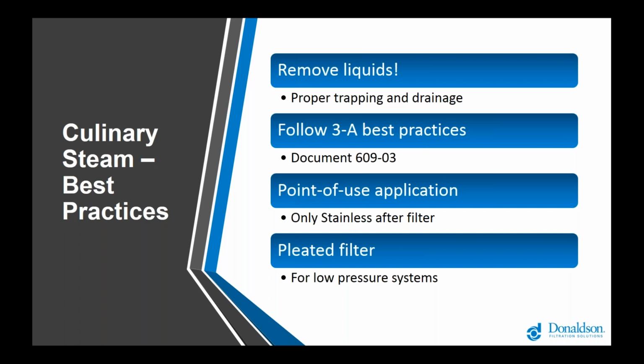And thirdly is use filters at points of use. So I've seen tons of systems where this is a single large filter located centrally, usually near the boiler, and then supplies a header and several points of use throughout the plant. And this is helpful.